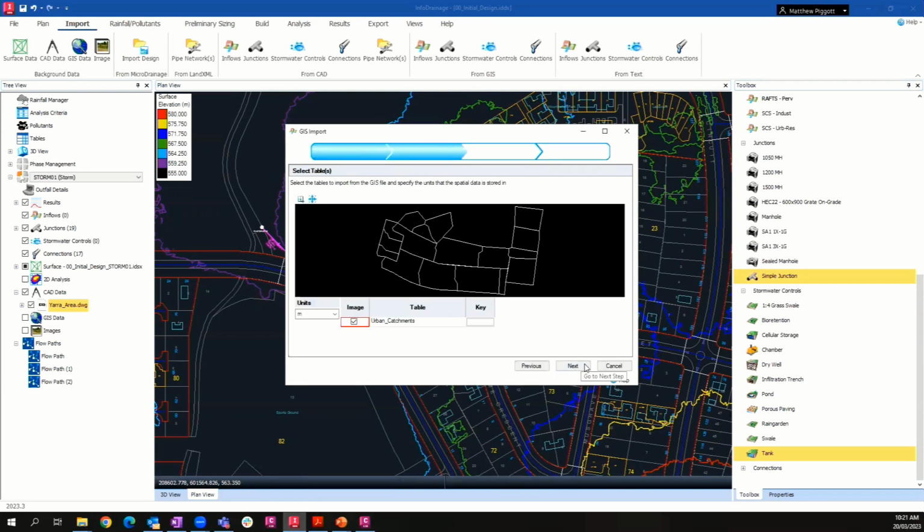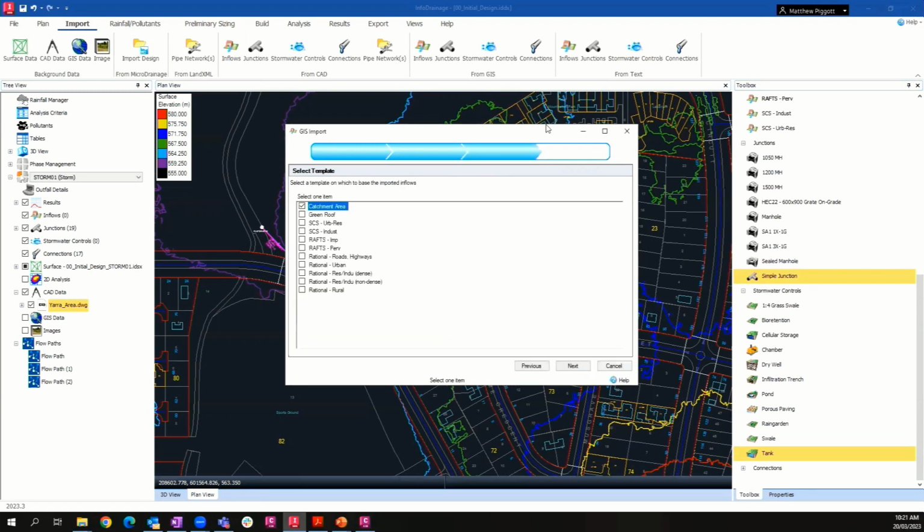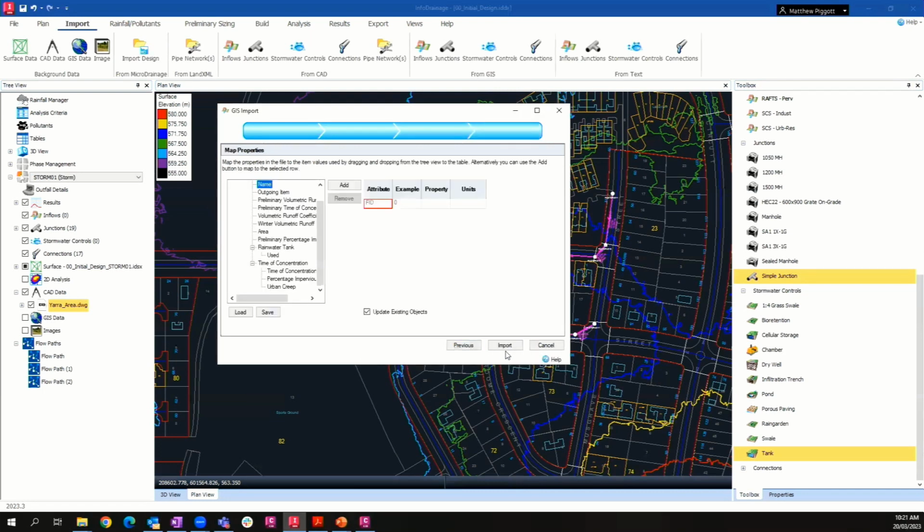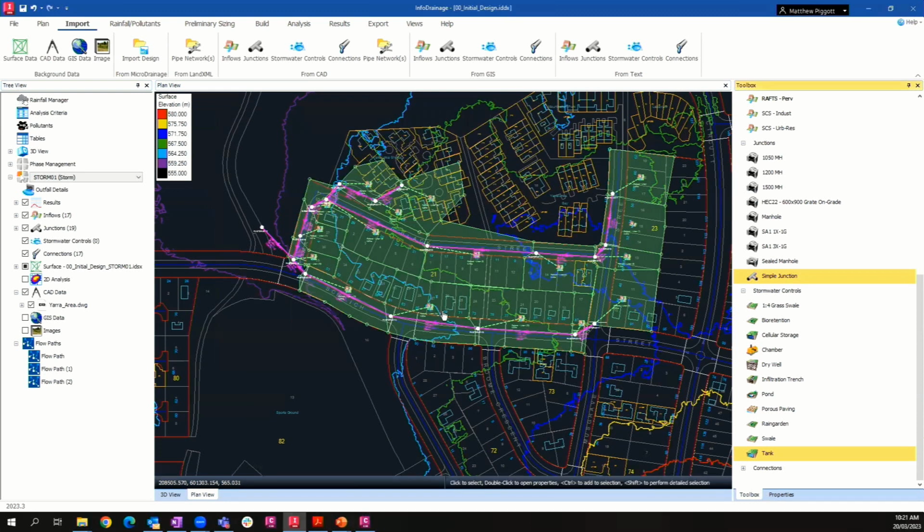I might mention here as well that we can use Civil 3D and its watershed development tools to generate these catchments for us. Now, as you can see, I'm able to select the required hydrology and parameters because I've uploaded in that object template earlier. So then I don't have to go through each catchment and set up the information. Now we have my catchments.